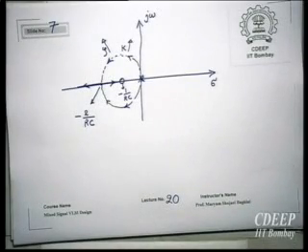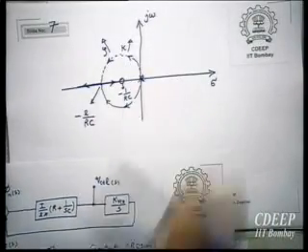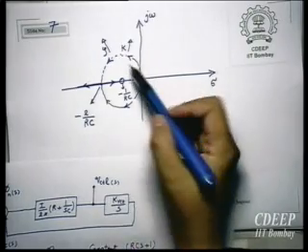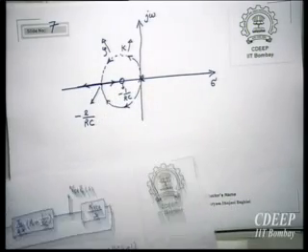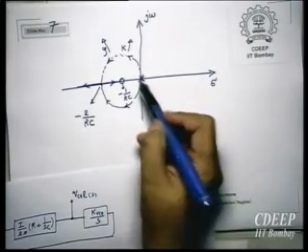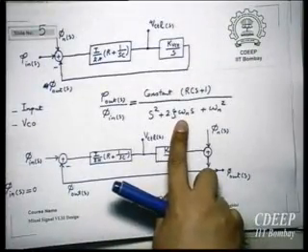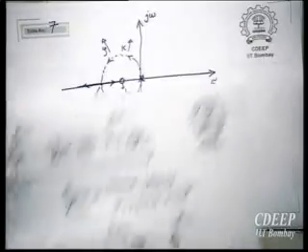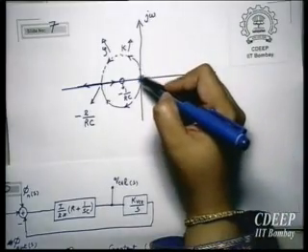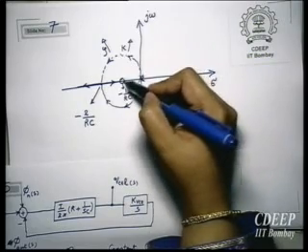So what will be the transfer function of the system? Anyway, it has a zero at minus 1 upon RC, and the positions of the poles are like this. Now there are 2 cases: either the poles are imaginary or the poles are real. In case the poles are imaginary, we start from here. Therefore, this can show some peaking. We had also 1 zero. However, if you notice, at least up to this point, the real part of these poles is before the zero.